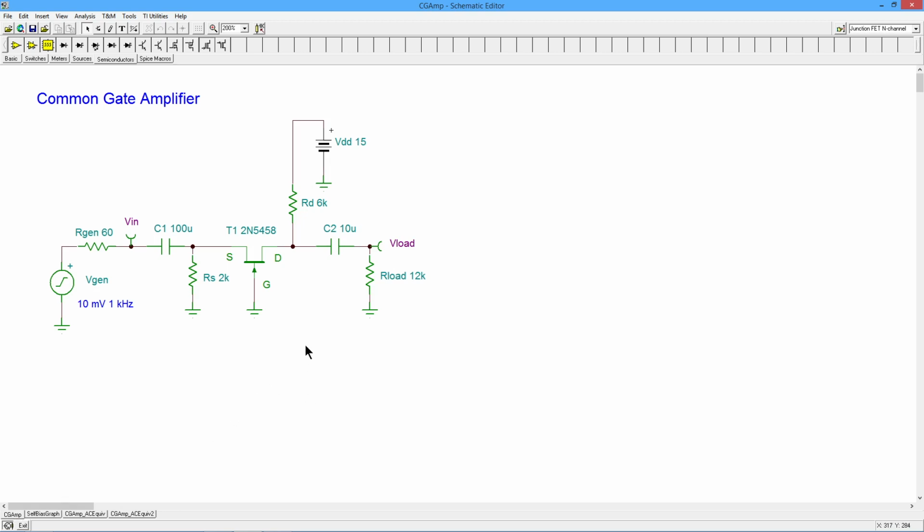If I was in lab doing this and I had some transistors, I would just measure the values for IDSS and VGS off, and from that we could calculate the value for GM0, right? We have a little equation for that. It's easy enough to do. It only takes an adjustable DC power supply and a DMM.